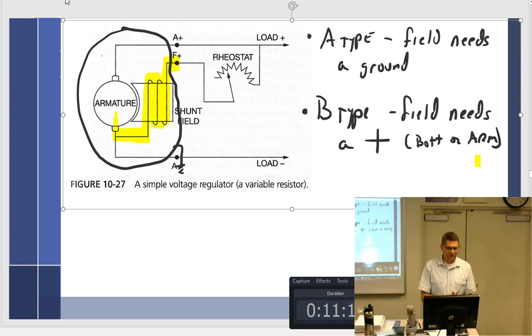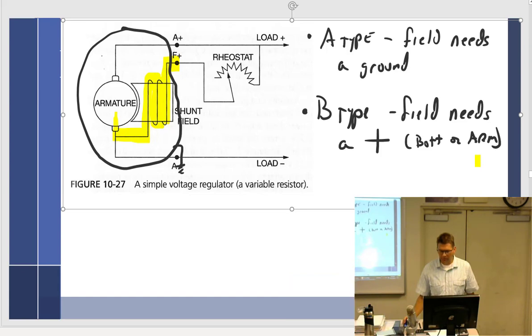So what does that mean? Why is that? So what's going on? No output from a freshly overhauled generator. Field windings are grounded. Well, inevitably somebody would say, we just need to flash the field. And inevitably somebody would go over and hook up a bunch of wires. Oh, you need to remove the voltage regulator. At that point I would pull off the voltage regulator and generator and send them out to have them both fixed.